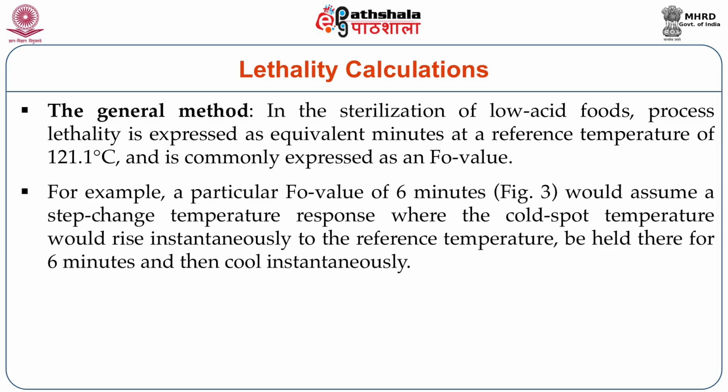For example, the F0 value of 6 minutes, as shown in the figure projected in the slide, would assume a step change temperature response where the cold spot temperature would rise instantaneously to the reference temperature, be held there for 6 minutes and then cooled instantaneously.